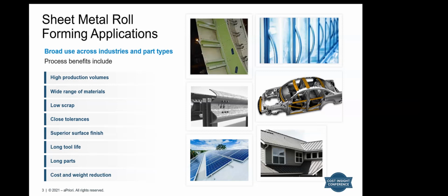In the aerospace industry, roll form parts include things like airframe stringers and interior components like trim and window frames. Jet engine components such as honeycomb seals, shrouds, and backing rings are made with roll forming. In the construction industry, roofing, gutters, door and window framing, shelving, railings, air ducts, and fencing all are made with roll forming.